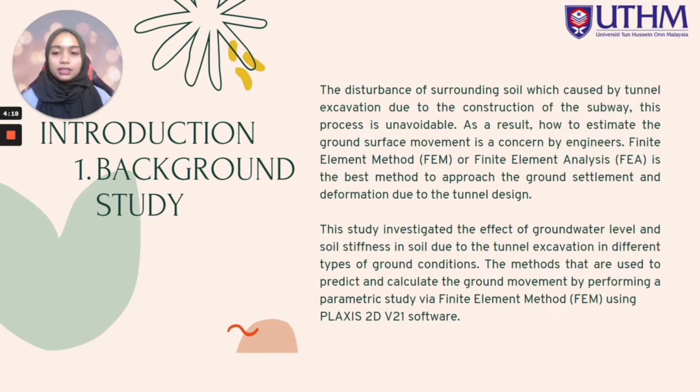For the introduction, I will start with background study. The disturbance of surrounding soil which is caused by tunnel excavation due to the construction of the subway is unavoidable. As a result, how to estimate the ground surface movement is a concern for engineers. Finite element method or finite element analysis is the best method to approach the ground settlement and deformation due to the tunnel design. This simulation is used to provide a structural analysis of how a particular model or design would react under stress in the real world.